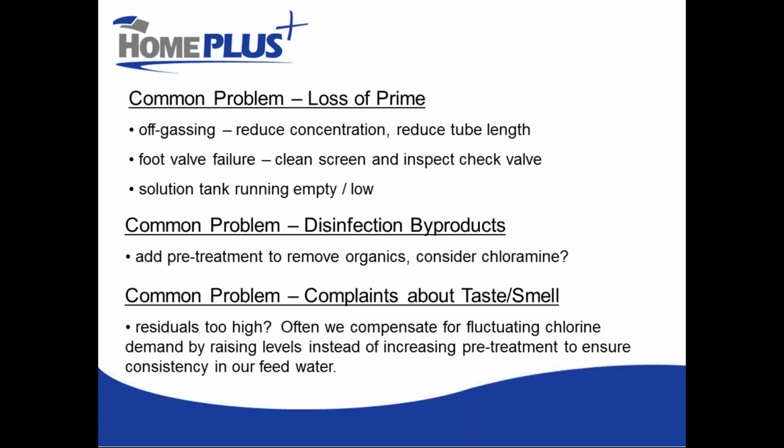And we have some guidelines as to maximum chlorine levels that we want to inject, and this often happens out of an honest attempt to solve other problems. One of those other problems can be a case where you have a long and extensive distribution network, and in order to get that 0.2 residual at the end of your distribution line, the first few houses on the line have to get 2 or 3 parts per million. That is a very big challenge to deal with.